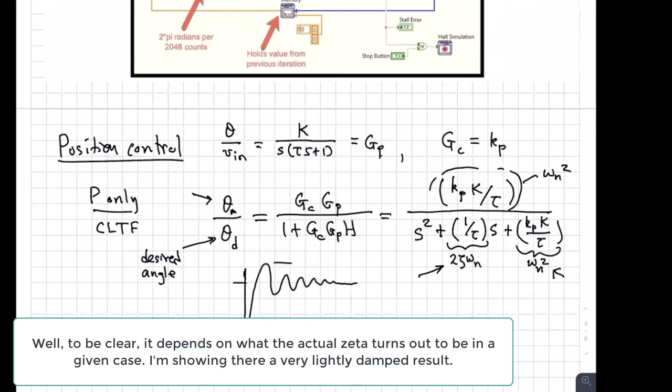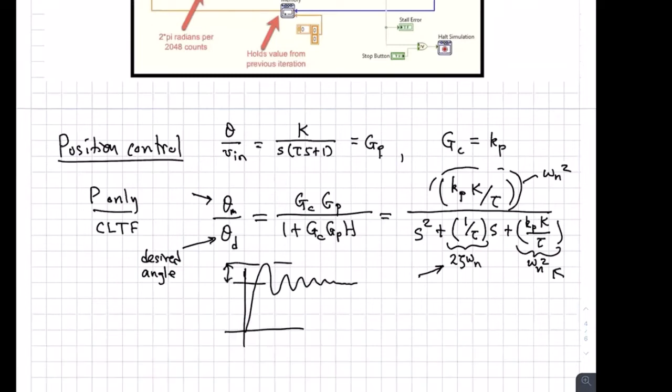One of the things I want you to measure in the lab is the overshoot. Sometimes we call that M sub P; in the Ogata chapter, he called it M sub P. How long it takes to settle to within a certain percentage is the settling time. How long it takes to get to the first peak is also important. Those are the specifications I want you to play with: M sub P, T sub P, and T sub S. Then you should also measure the steady state value.